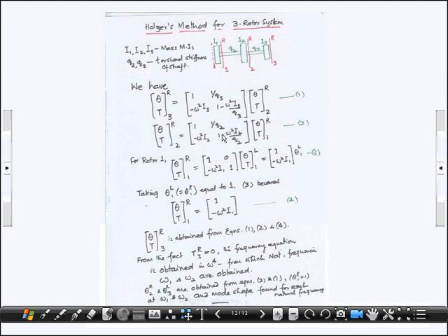Now, the state matrix at R1, that is the state at this point, can be related, as I told you, from the point matrix of this rotor, which is simply [1, 0; minus omega square I1, 1] times the theta, t to the left. To the left of this rotor, we know the torque to be 0.